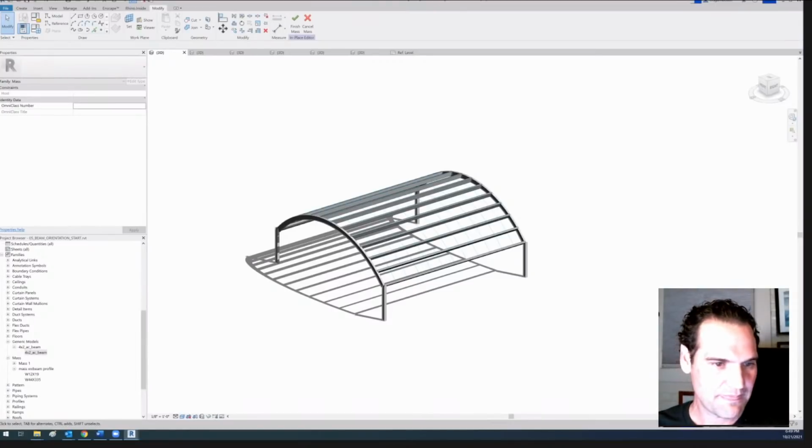So in that situation, if I'm using that now to create my model, which is then creating my documents, are you leaving that beam in place? Are you categorizing it as structural framing at a minimum, just to make sure things look and act the way you want on the documentation side, as well as the model use side?